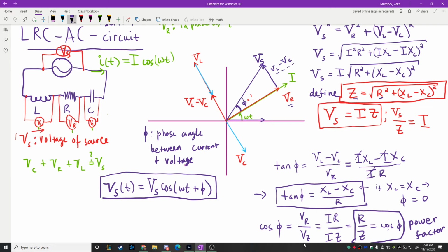So it happens to be the case that if you have these perfect values of your inductance, capacitance, and your angular frequency, then you can get it so that the voltage of the source and the voltage of the resistor are in phase with each other, that the voltage and the current are basically in phase with each other. And the reason why this is related to power is because if the voltage, which is effectively how hard the source is pushing on the electrons, right? And the current, which is how fast the electrons move, if the force on the electrons and the direction they're moving are always in phase with each other, right? That means that your system is basically outputting all the possible power that it could, without any of it being sucked up by the fact that there's a lag between the motion of the charges and the applied force on the charges.